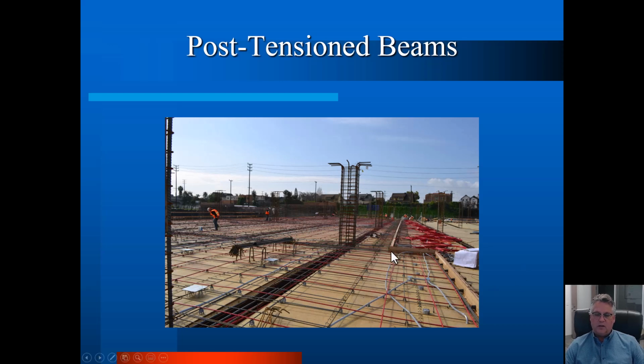We're going to come back to this slide a little bit later, but this is a construction joint. Most of the time, the contractor cannot pour the entire floor at one time, so it's broken up into various pours with construction joints. And that sometimes is a problem in reinforced concrete, not really in post-tension concrete. And the problem is the lapping that's required in reinforced concrete or mild steel. You can only go 60 feet with a piece of rebar. That's the longest a piece of rebar can be trucked on the highways in California. So you're left with 60-foot pieces. And if you need more than that, you've got to start lapping.